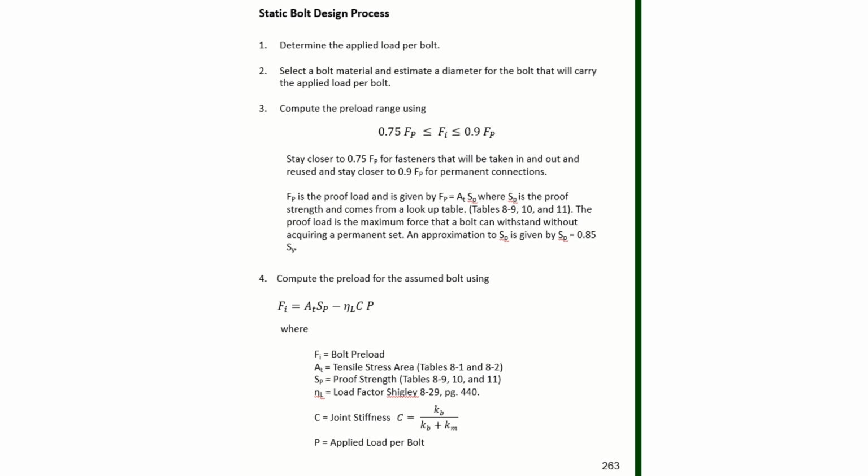And that's if it's made of mild steel. Then I can get an idea of where I need to be to estimate the diameter of the bolt based on the actual applied load that I have for the situation I'm looking at. So you need to get your reference point and remember a reference that you can use throughout your career.